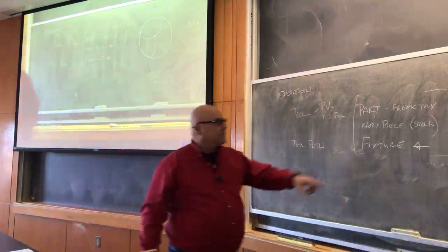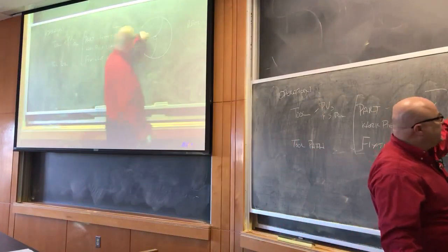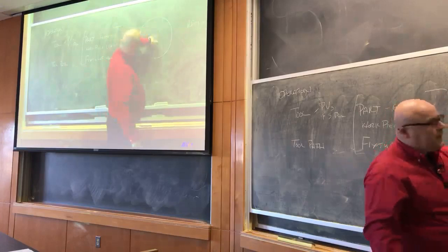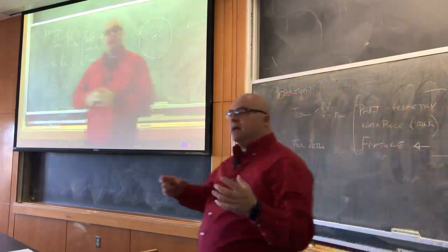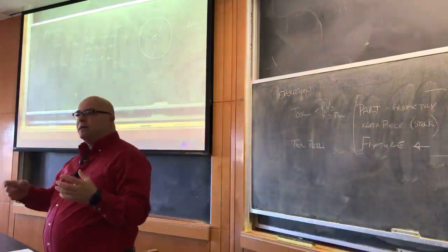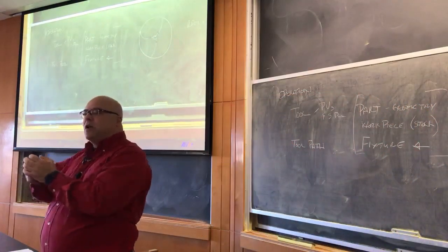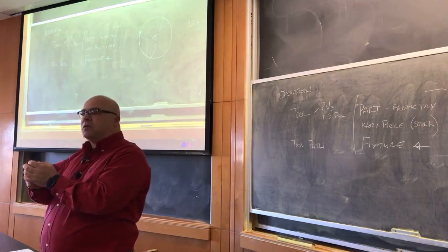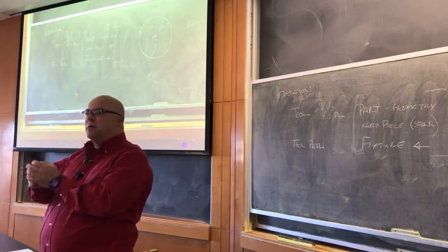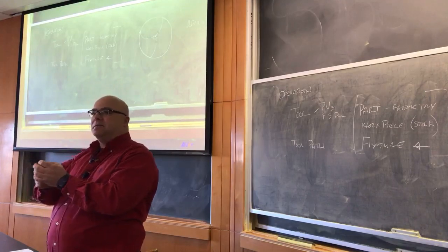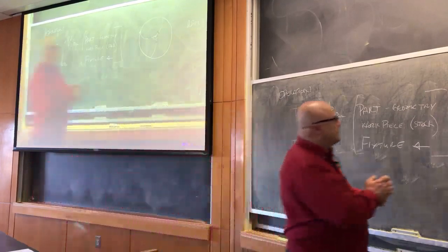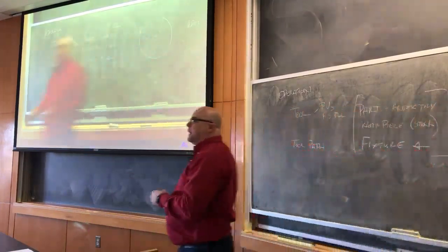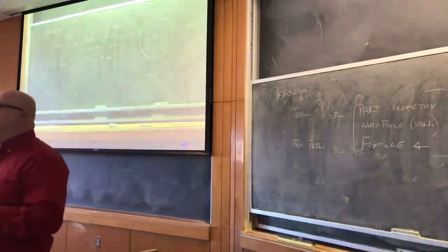But basically what happens at the center of the tool, I wonder if anybody's ever studied this: how far out from the center do you have to be before there's really cutting happening? When you're inside that zone, it's just pushing the material around, which means the force of the motor is pushing the aluminum out of the way. So we don't like to plunge directly into it. So if I don't want to plunge and I have to make a pocket in the center of the part, what could I do?